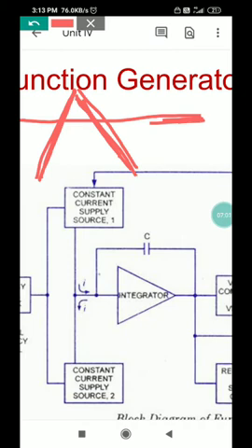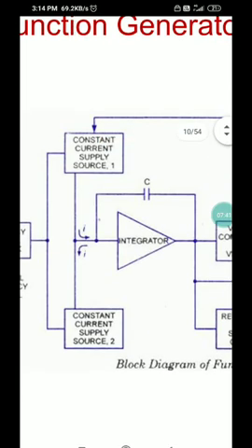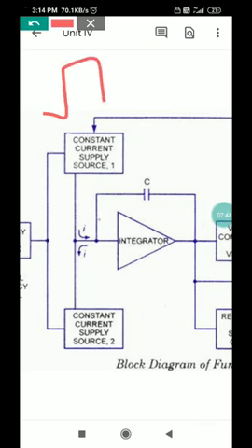So as and when your output is less than threshold, this kind of output you will get. On the rising edge you will get this edge, and as long as it is more than your threshold, it will keep flat, and as and when this negative slope occurs and this line crosses at this point, the falling edge starts. So your output of multivibrator is of this type.